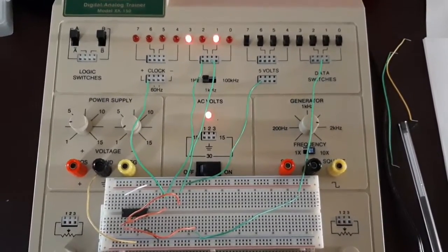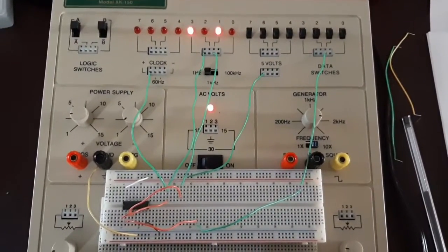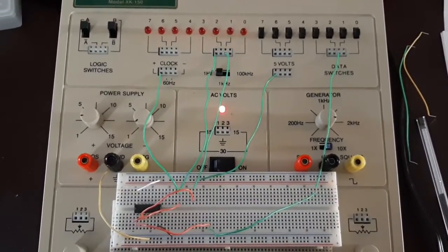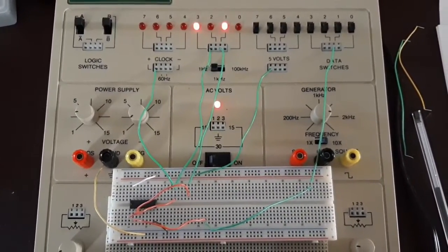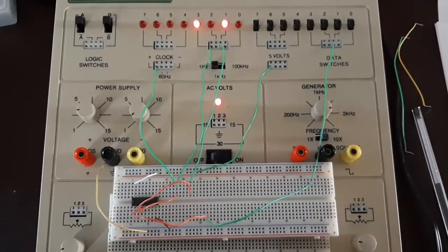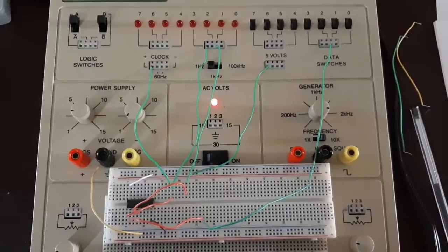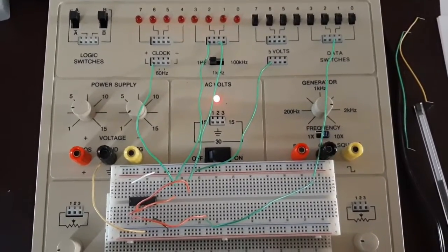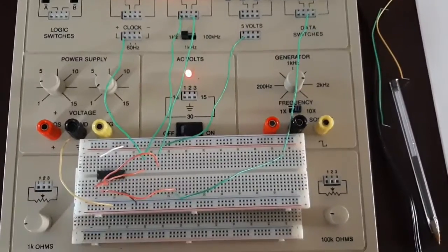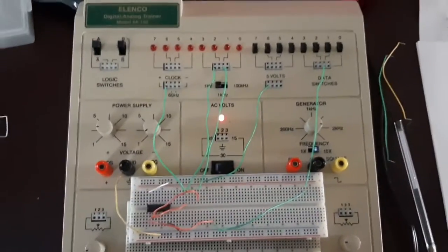That is because one input is consistently low, and for an exclusive OR gate to have a high output, one of the inputs has to be high. So anytime the square wave goes high, the output will also be high, because that's the only time it will receive a 1, since the input A is consistently 0. And that's how that looks.